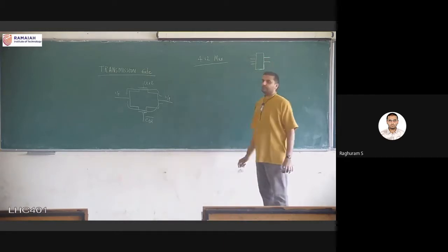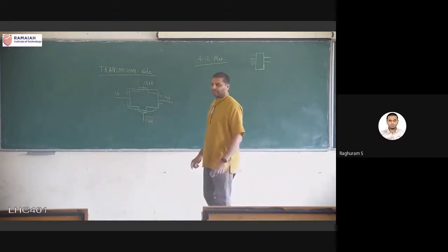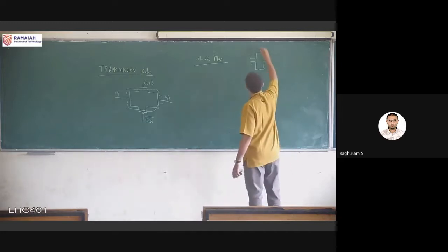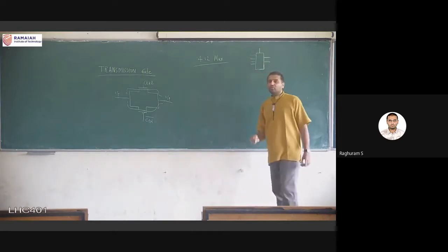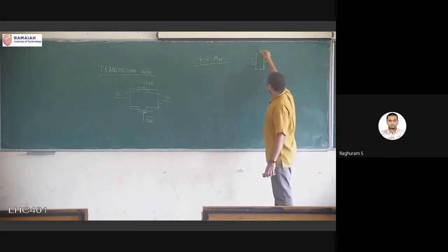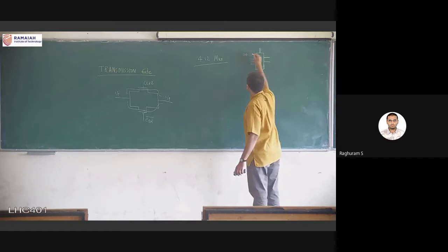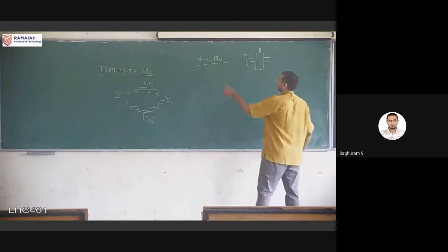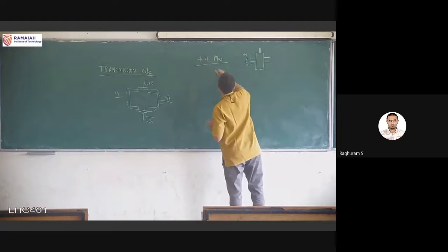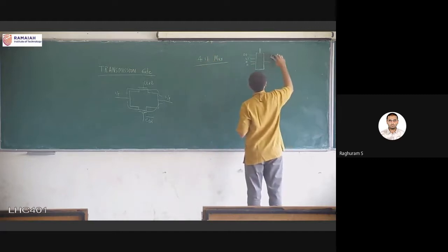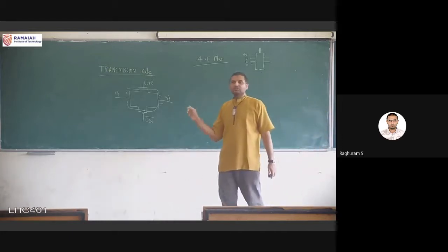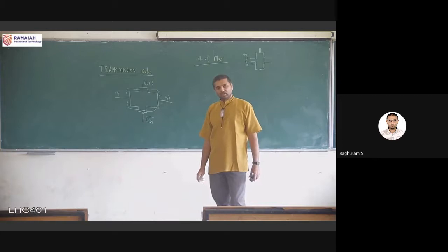Basically the control signal cannot be a 1-bit control signal. It has to have a 2-bit control signal. So we can call this as the 0-0 input, 0-1, 1-0, 1-1. Sorry, that is a 4:1. So let's do 4:1 multiplexer. For each input combination, one of the signals gets passed to the output.